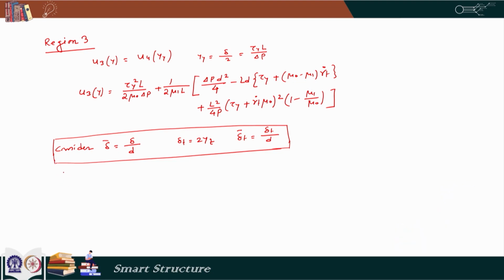So, after that we will find out the equivalent damping coefficient, and for that again we have the same approach. We first find out the total flow rate, and then we equate that total flow rate with a flow rate which would have been there if there was a uniform velocity um, and that would give us the equivalent uniform velocity um, and then we divide that velocity by the force, and that would give us the damping coefficient. So, first we have to find out the total volumetric flow rate.